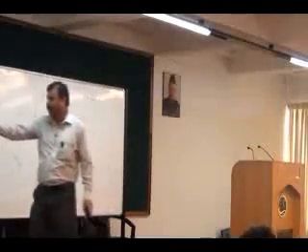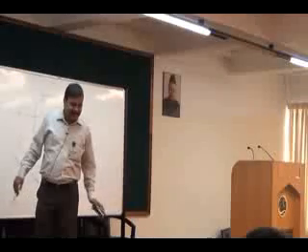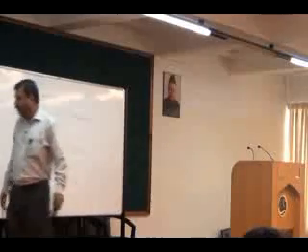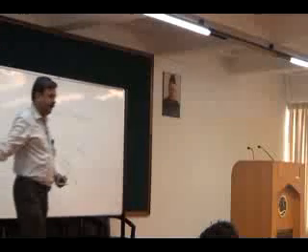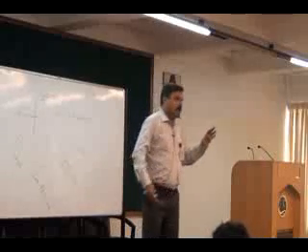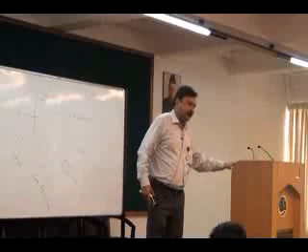So you have a starting motor. The starting motor is an electrical motor, so it needs power. Part of the mechanical energy available is converted into electrical energy by the alternator and stored in a battery. This electrical energy may be supplied for the starting.